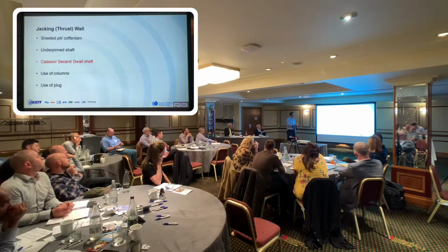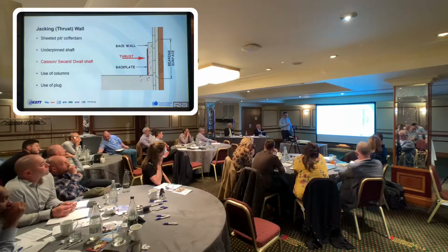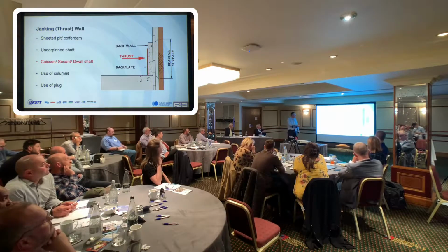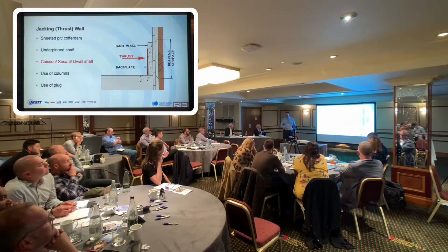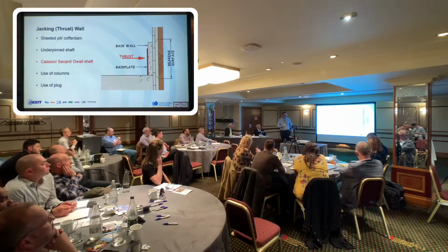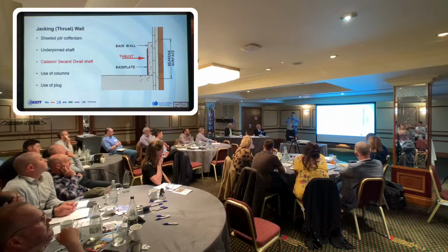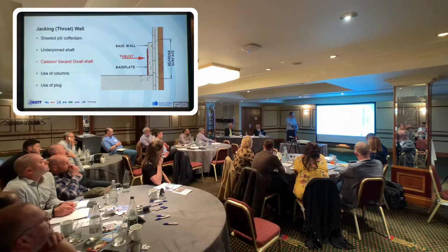Whether it be a secant or a diaphragm wall shaft, it's very much the same. You can see that the back wall is cast. The units are in there now. Generally speaking, the precast concrete units can take a little bit more than the sheets. The reason is when you put a load into it, it starts to act in the hoop. Whereas if you've just got your sheeted wall, you're relying on the resistance of that sheet and the ground behind it. But you can see there.